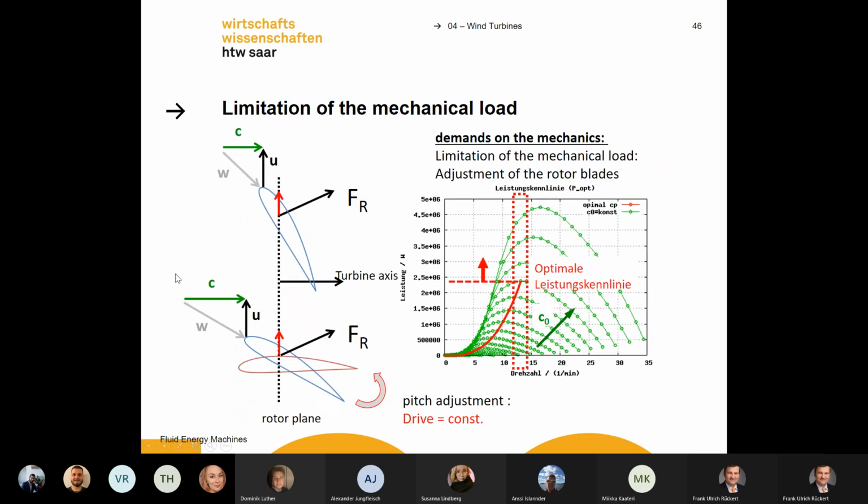Okay. Of course, your optimum depends really much on the pitching. You can rotate the plates a bit to fulfill the demands of the wind velocity, to get your triangles right, and then you can change the position on this efficiency curve a bit by rotating the plates.